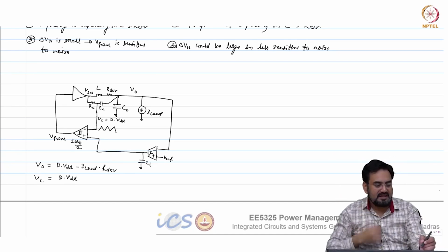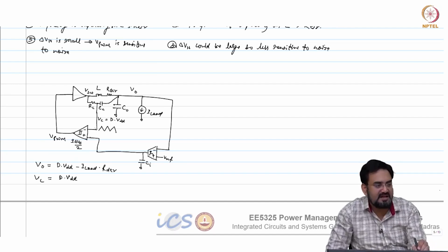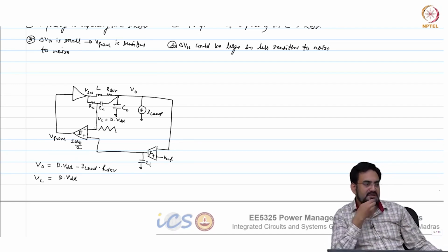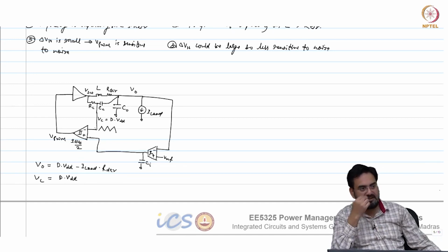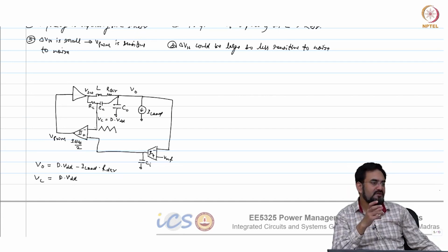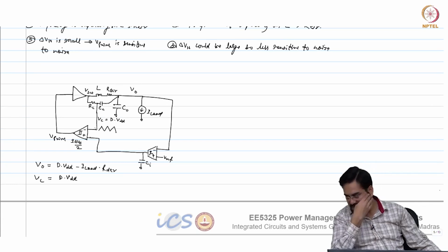The other thing is, I am trying to keep this delta Vh large here due to noise reasons. So my output has to wait until that time before your comparator trips. So this large Vh window degrades the transient response. Regulation can be done with the integrator, but transient cannot be improved. So is there any other way I can improve the regulation and transient both?